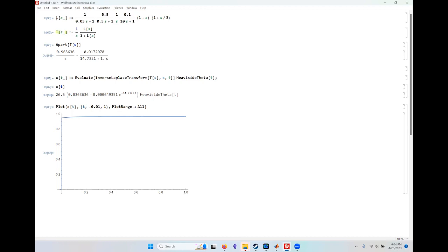Now this is the open loop transfer function. The closed loop transfer function is just the open loop over 1 plus the open loop, right? That's the negative feedback form. What's this 1 over s? I want to examine the response to a step input. Actually, my step is 1.6 u of t, since the steady state is 1.6.